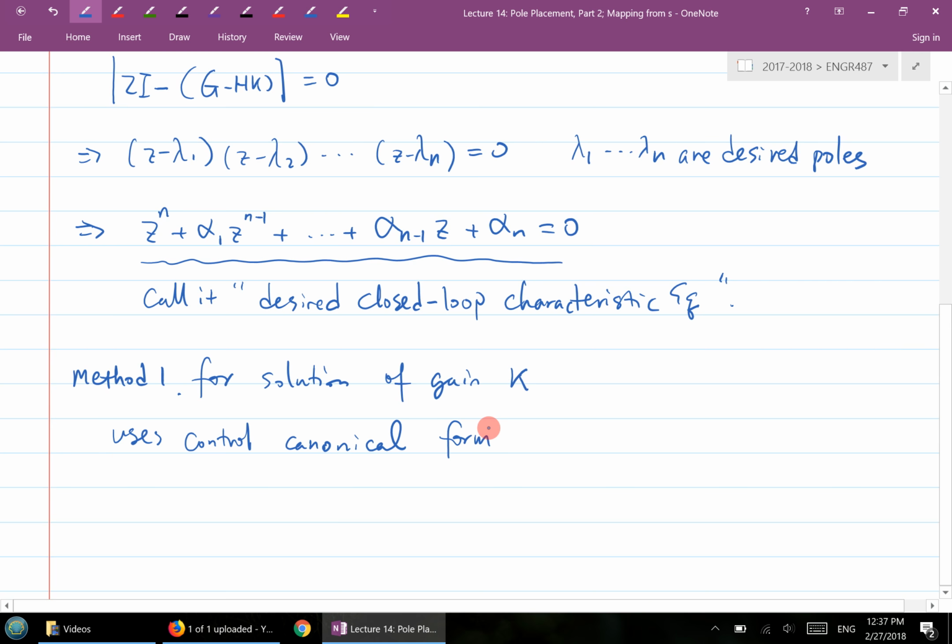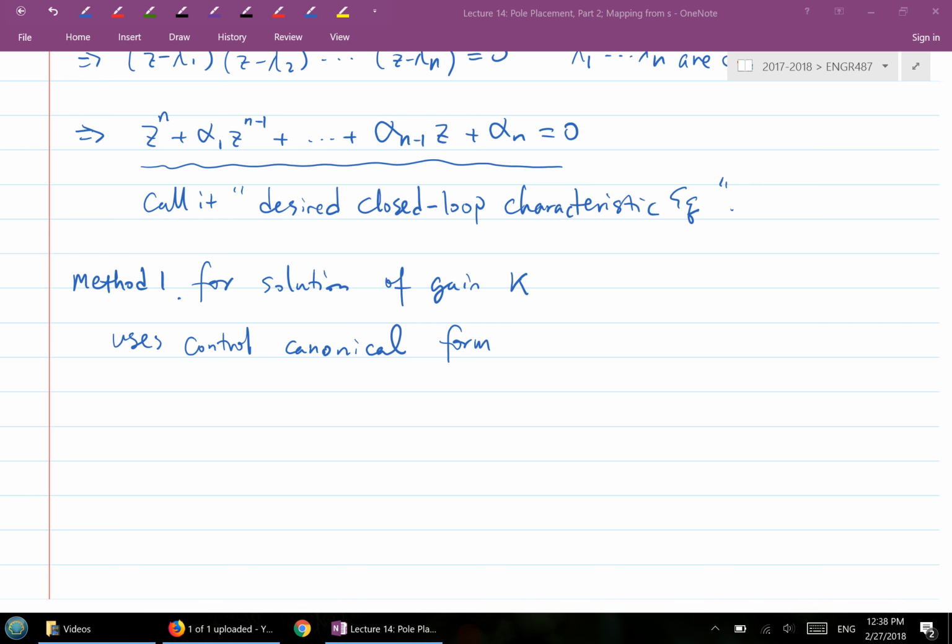the first step, of course, is always the continuous system, and from the continuous system you can derive the pulse transfer function by considering a zero-order hold equivalent, right? And then from the pulse transfer function, we can draw different types of simulation diagrams. One type of simulation diagram gives us the so-called control canonical. Another type will give us the so-called observable canonical, right? And another type can give us the so-called Jordan format. So from here, let's consider the control canonical form.